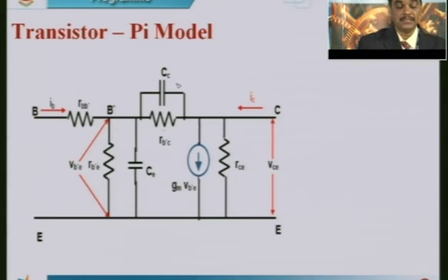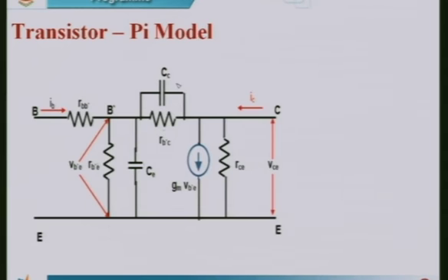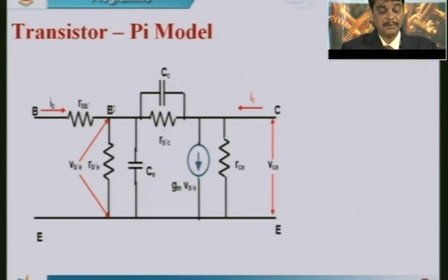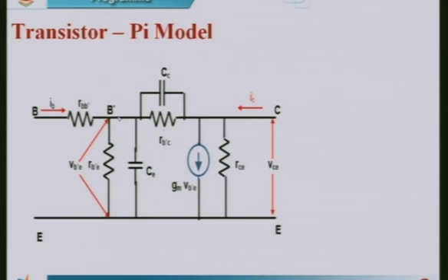If you observe, instead of a base B, we are considering B dash and B, where B dash is not physically accessible because the base is lightly doped, and the conduction goes through a semiconductor path. Therefore, we connect that B dash, where we have to define many parameters. Between B dash and the emitter, because of this conductivity, some resistance exists.